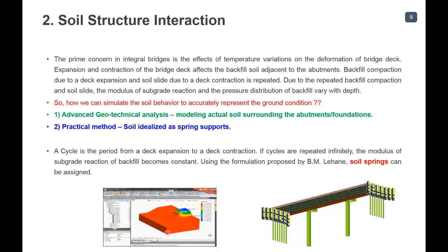So how do we idealize this soil to springs? A lot of research has been done, and the pioneer researcher BM Lehane has proposed the formulations for the soil springs. As these cycles are repeated infinitely, the modulus of subgrade reaction of the backfill becomes constant. These formulations have been used in MIDAS Civil as well. We'll see that later.